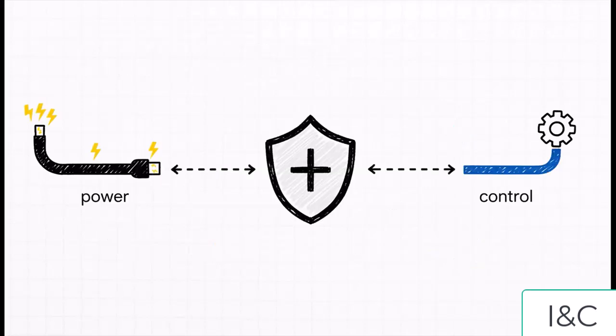Okay, next up is IEC 60204-1. This one's a huge deal, especially if you're working with industrial machinery in Europe. Its whole reason for being is safety and making sure things work correctly. The big takeaway from this one? You must physically separate your power circuits from your control circuits. Why? To stop malfunctions that could lead to some really, really dangerous situations.